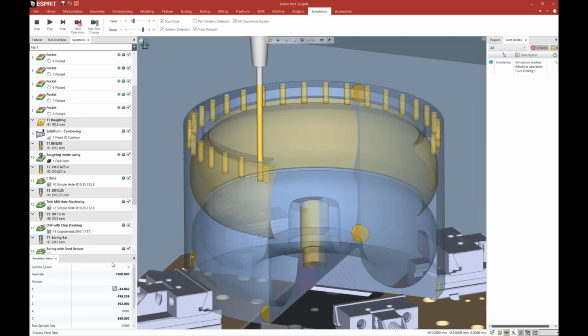Okay. So first thing I'm going to be looking down here. I'm going to step through this. First thing that happens, we kick onto that initial RPM and feed rate. It gets down to depth, and then it kicks up to 5,000 RPM, and then goes to the next final depth, still at 5,000.